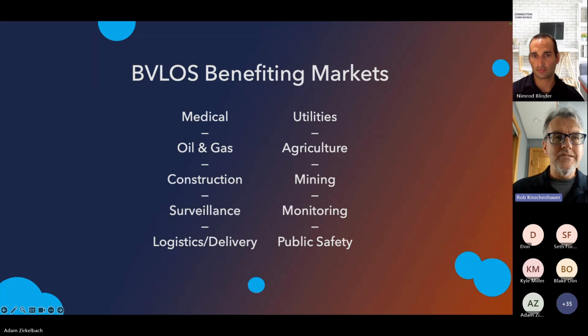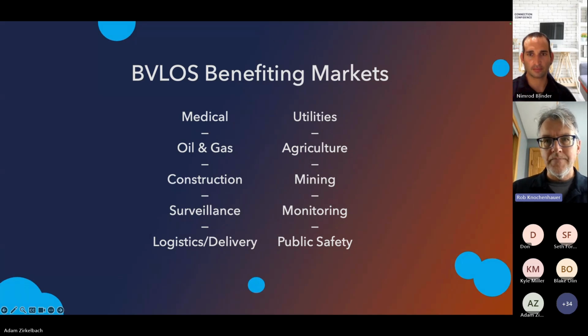So the way it's set up is if you're closer than 3 miles, you need to do some coordination with the airfield that you're operating near. So if it's an airport and it is a controlled airport, you have to apply for an airspace authorization through the drone zone, because you can't actually use LAANC for an approval where you're using it with an operational waiver. So when you apply for your approval through the drone zone, you would have that opportunity to do that coordination with the air traffic facility where you're looking to conduct a BVLOS operation. So yeah, we have done it and it's worked out pretty well.